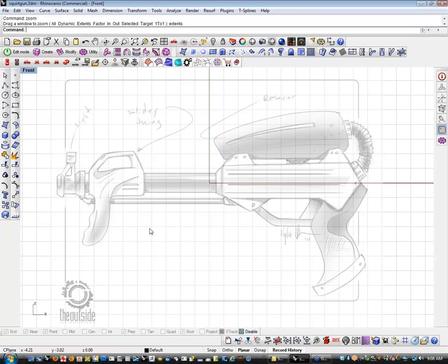So instead of trying to do this as one complete T-Splines model, which would not be the way that you'd do this if you did it as a NURBS model, we're going to break it up into a couple of different elements and then let those objects intersect. Ideally, what you would do is use T-Splines for what T-Splines does best, which is modeling the organic stuff, and then finish the detailing out in NURBS.